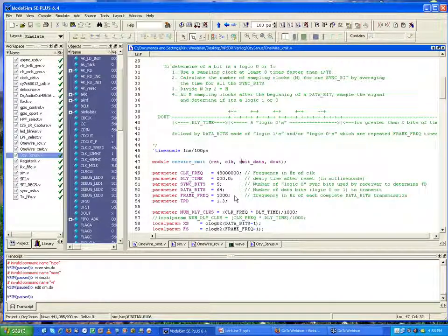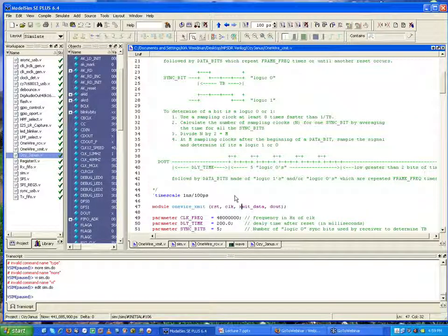Okay. And the sync bits are merely just for helping the receiver know how fast the data is coming. And I'll show you how that actually works. In fact, maybe we should just go through it now. So on the receiver side, if you were to get one of these sync bits, either a logic 0 or high, you can detect where the signal goes high.